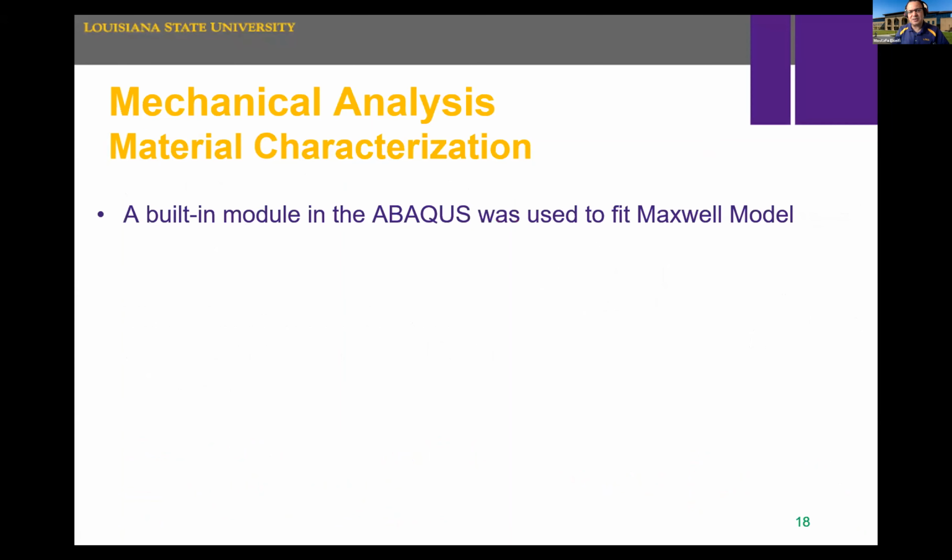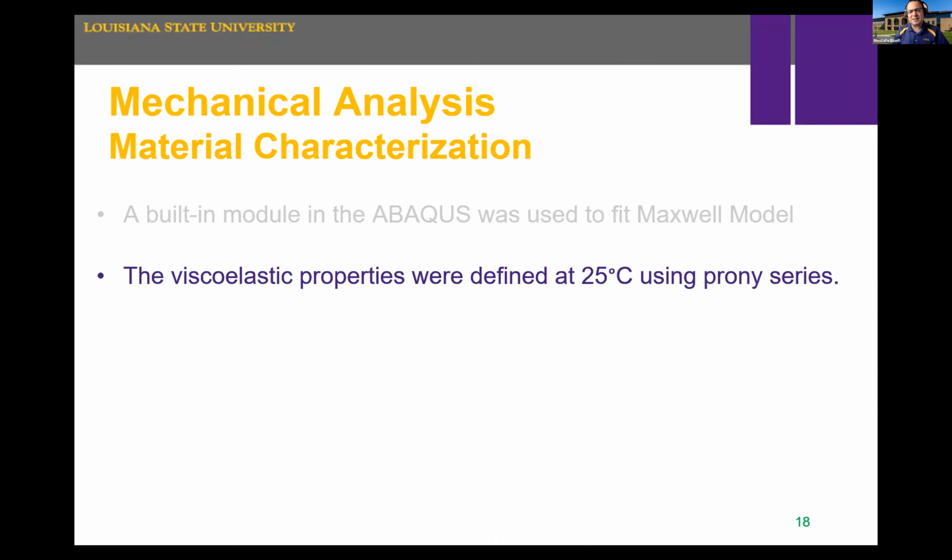To fit the generalized Maxwell model, there is a built-in tool in Abaqus that allows you to do that. You enter your experimental data, and then it determines these material parameters so that you have an accurate representation of the viscoelastic behavior of the material.